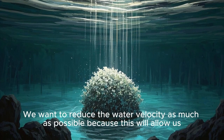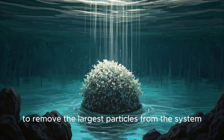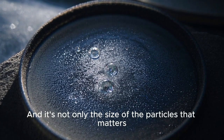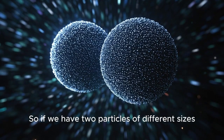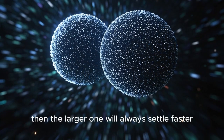We want to reduce the water velocity as much as possible because this will allow us to remove the largest particles from the system. And it's not only the size of the particles that matters, but it's also their density. So if we have two particles of different sizes but the same density, then the larger one will always settle faster.